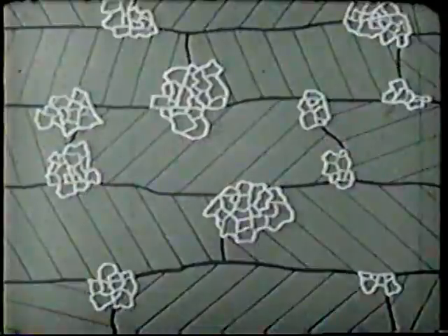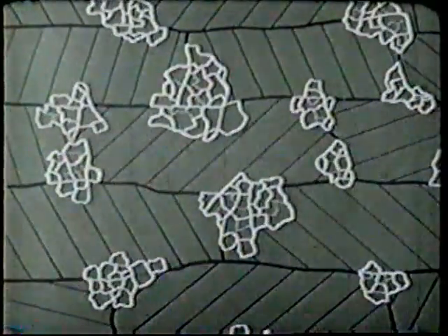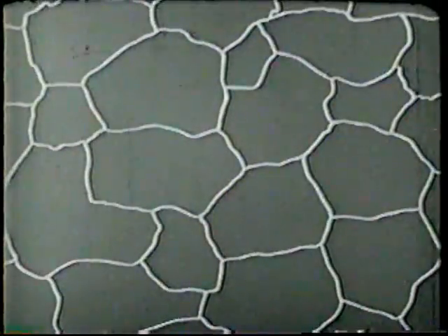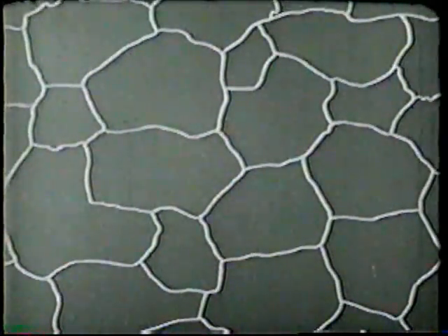Annealing first relieves the internal stresses caused by cold working. As the metal is heated to recrystallization temperature and above, the nuclei of new grains are formed from the fragments and crushed particles of the original grains. These nuclei may merge with other fractured particles or with portions of the original grains, growing into new stress-free grains. The metal is now annealed and in a soft condition for further forming.